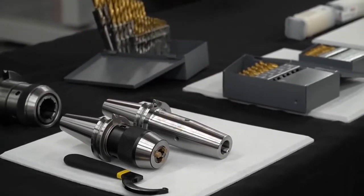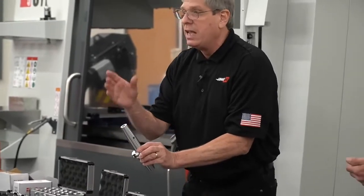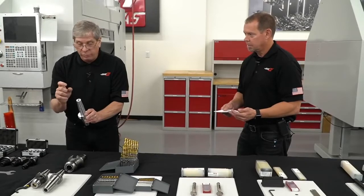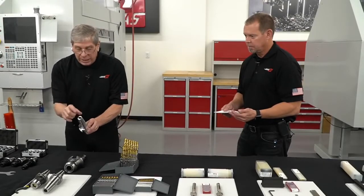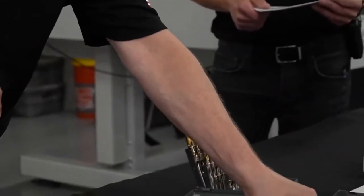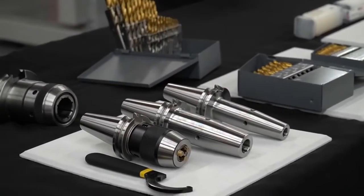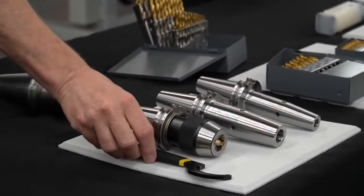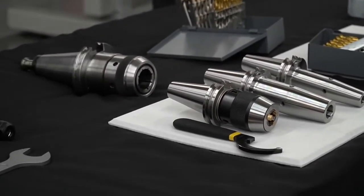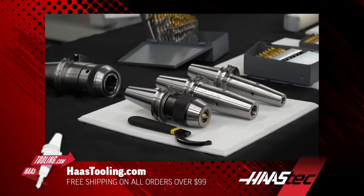I love these holders because they've got the holes right in the face for the through spindle coolant, so you don't need slots down your end mill, or some have a hole through the center of the end mill. You can put any end mill in there and have TSC coolant spraying right at the tip of the tool, down the flute. So there's a couple of sizes of shrink fit, and here's a drill chuck, comes with the key. Fantastic offering of new tool holders that'll be coming soon. Now we've gotten a lot of requests for these, and these will finally be coming soon.